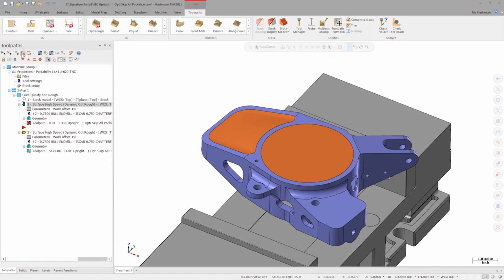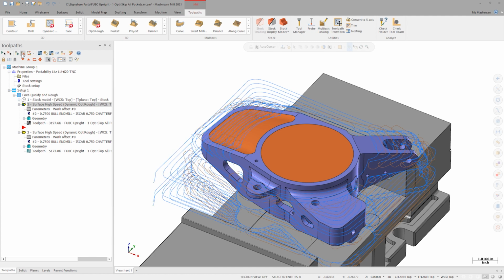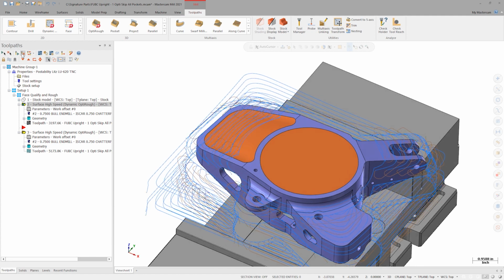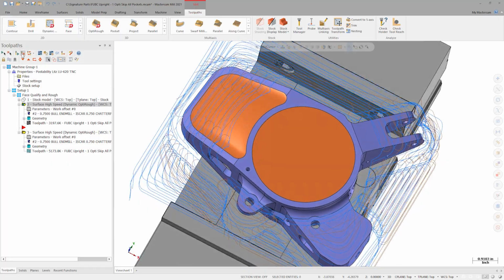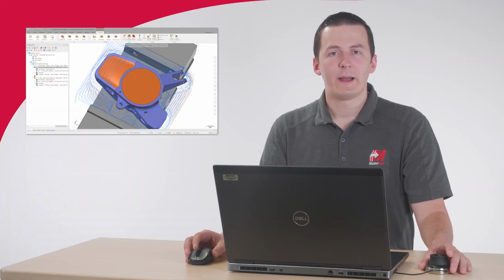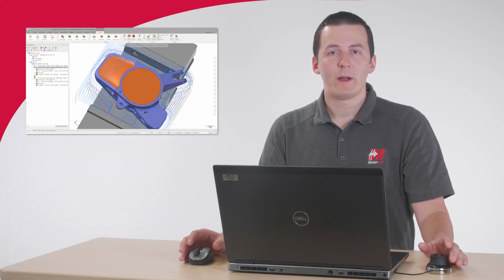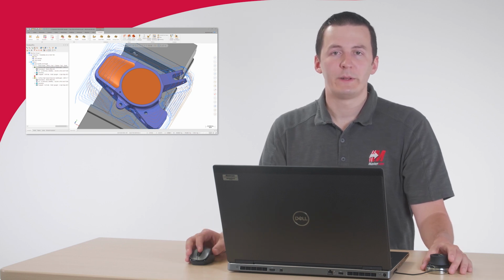After regenerating the toolpath, we can see that all the green entry motion sections have been eliminated. This method of avoiding pockets is completely reliable, but requires lots of manual user input, and as we are about to see, it leaves extra material behind.